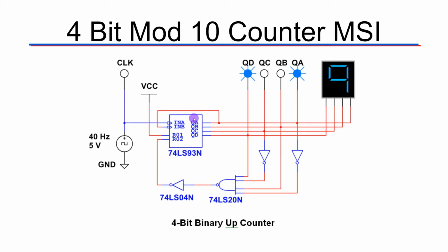So essentially we have 4 flip-flops wired together as we would in a synchronous counter, and we have access to each of those individual bits. We're going to do 3 main parts of this build. We are going to wire up the counter and make sure that we can use the clock signal to make it count. We're going to do the same thing where we have a binary value indicator, which is an array of LEDs or probes, specifically showing the individual signal outlines here.